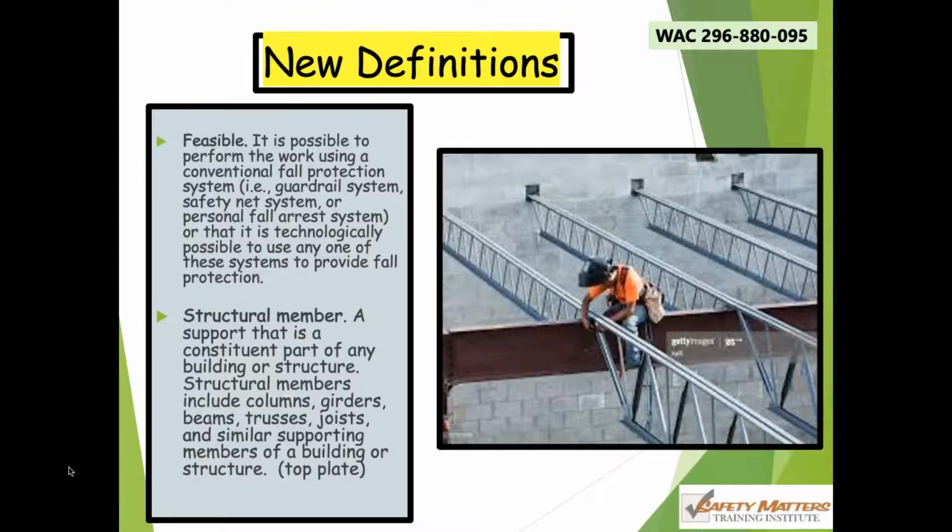They've put in this new definition, feasibility. Feasibility comes up in scaffold work. Anytime I'm going to be erecting a scaffold, it's up to the competent person to determine whether or not it's feasible for his crew to be in fall protection. So what's feasible? It's determined as, is it possible to perform the work using a conventional fall protection system? What's conventional? Guardrails.